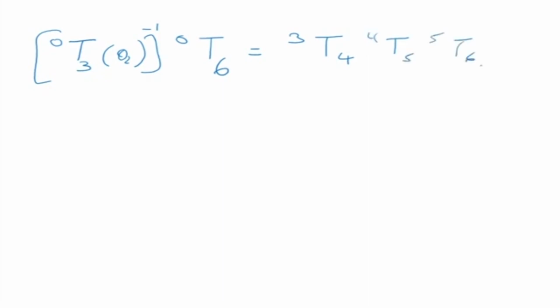Okay, we said that we are multiplying in a particular sequence. First we did, if you remember, 0 to 3, and then we did 4 to 6, and then we removed theta 1. So now in this matrix theta 1 and theta 3 are known. So what is not known is theta 2. So theta 2 is unknown now. So on the left hand side you have one unknown. On the right hand side you have theta 4, theta 5, theta 6. So now what we do on this, let's call this equation number 4.